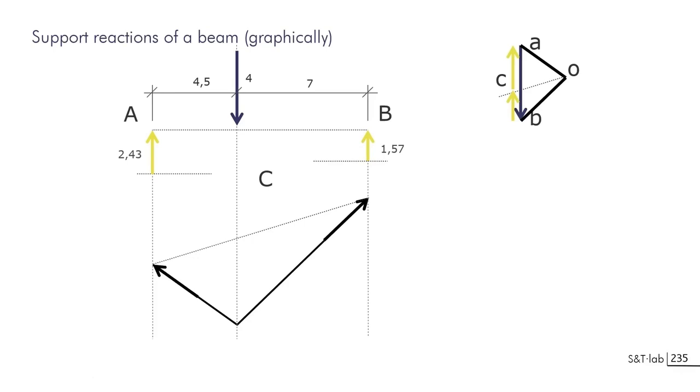You see that this geometry is not totally proper compared to this one with a horizontal line. So you can use a specific process in which we'll be changing the direction of the force. You just need here to draw the closing string horizontally through this point C that you know, to put somewhere the new pole and get new rays that give you the new orientation of both sides. And that will be revealing the bending forces as we can see just after.